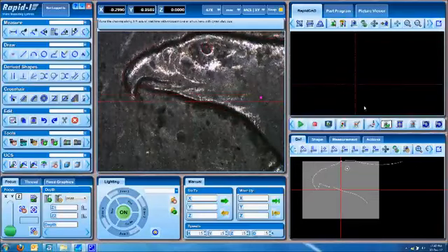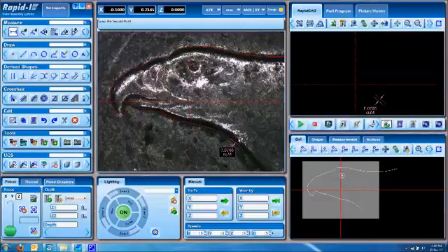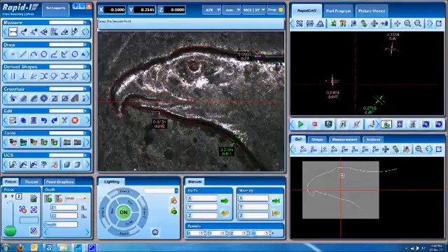You can visualize the deviations of the manufacturing with respect to the original design. Now you want to quantify that. Just switch on the digital micrometer, go close to the drawing, click on it, it snaps, and you get the distance, the gap, immediately on the screen itself. So you can now visualize and quantify exactly what the deviation is.